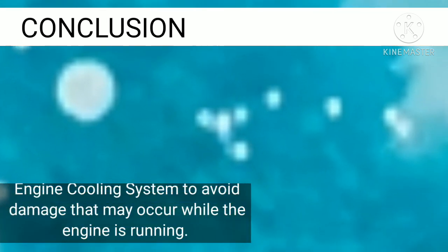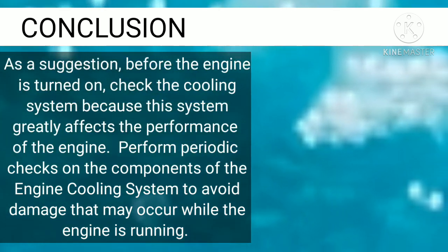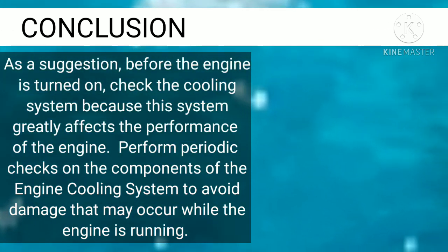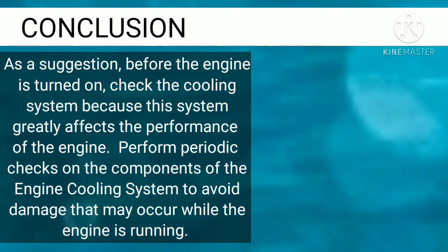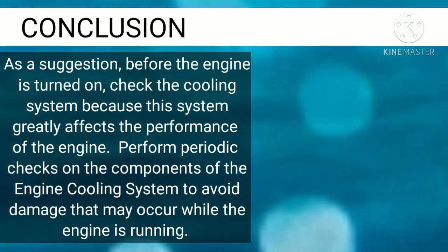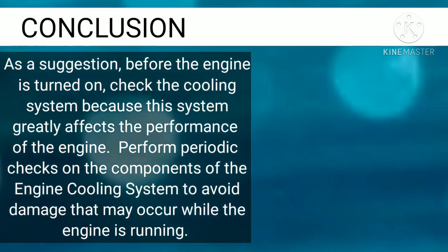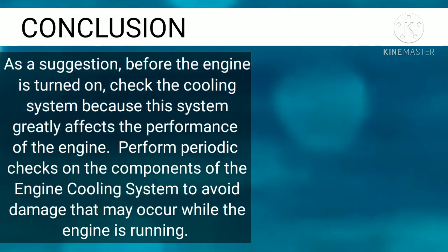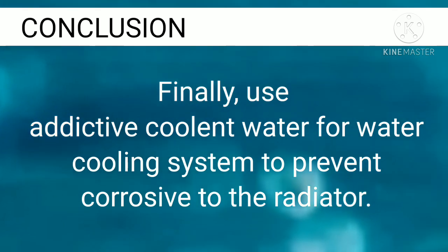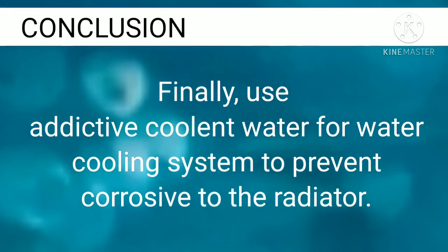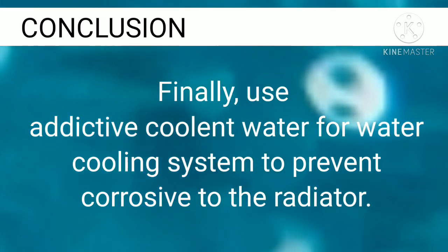As a suggestion, before the engine is turned on, check the cooling system because the system greatly affects the performance of the engine. Perform periodic checks on the components of the engine cooling system to avoid damage that may occur while the engine is running. Finally, use additive coolant water for water cooling system to prevent corrosion to the radiator.